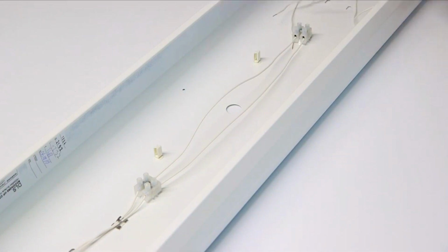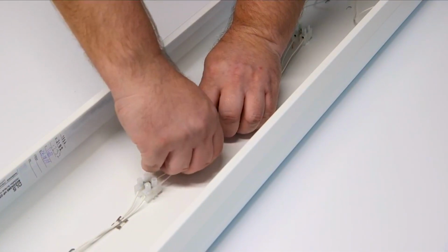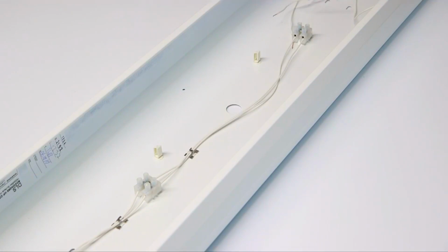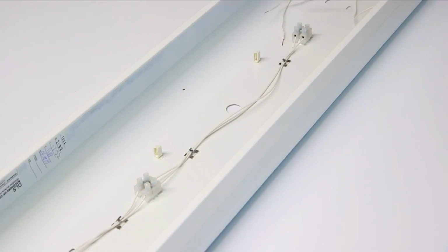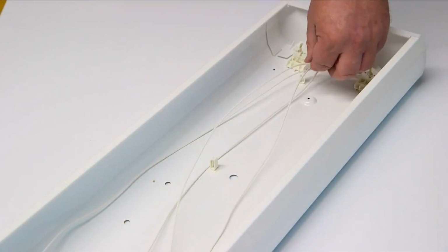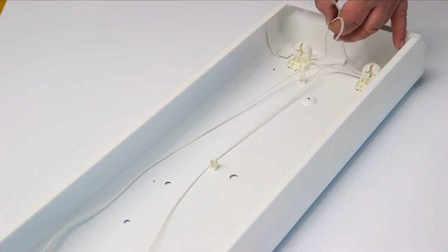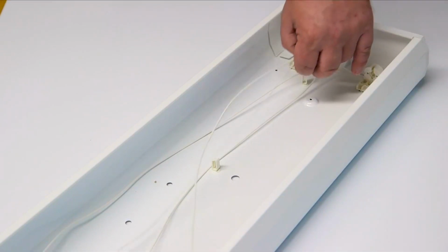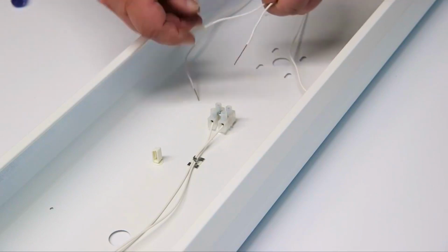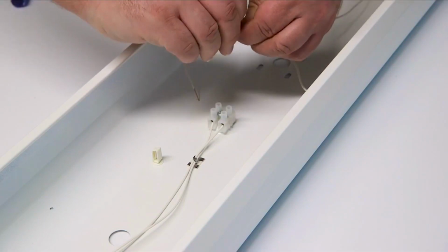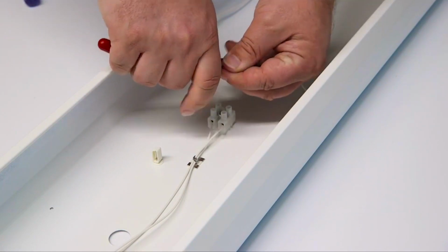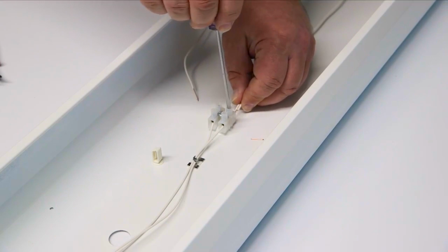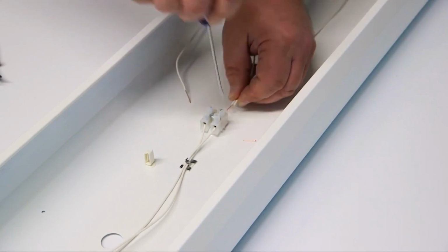It is important to note that when wiring the fitting, the wires are routed in the most efficient way and secured in place. Here we are using some cable clips to secure the wires, which we have stripped beforehand. One wire from each tube connector will serve as the live wires, the other 2 will be the neutral wires. We have selected the top wire from each connector as the live wire. These live wires are then both secured into one side of the terminal block that then connects to the mains input live.